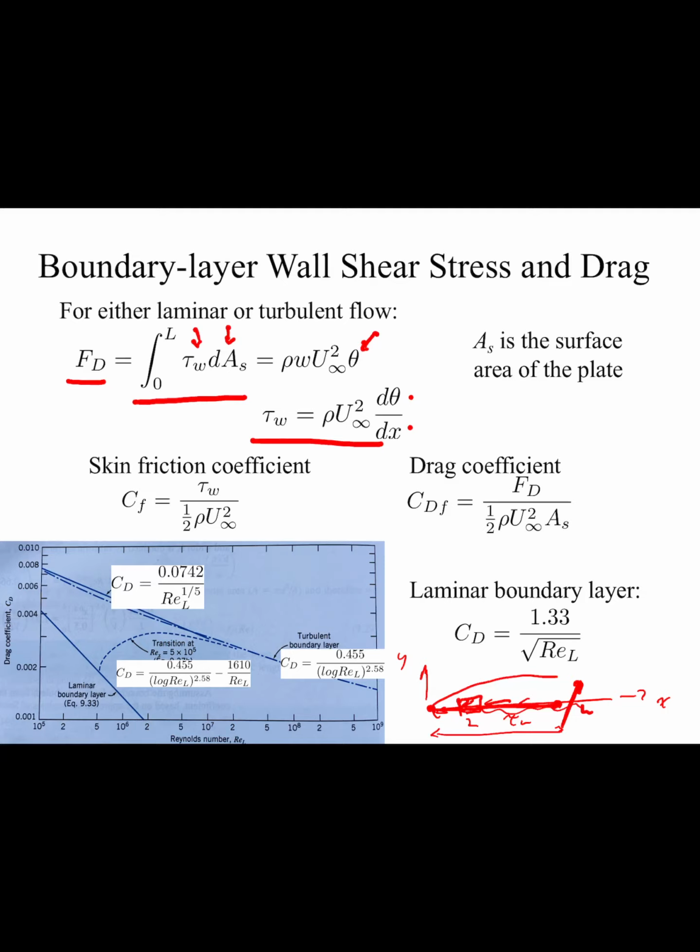but it allows us to immediately calculate, if we have a velocity profile, the momentum deficit, the momentum thickness. And then if we have it at two locations, we can calculate the shear stress, because we need to calculate a derivative from this. So this is a powerful tool, and it should make sense.